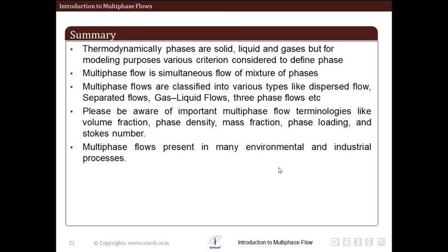So to summarize, what you should take home from this lecture on the basics of multiphase flow is that thermodynamically there are three phases, that is solid, liquid, and gas. But from a modeling point of view or an industrial point of view, we have different criteria for defining phases, and we may have a liquid-liquid system, but still treat it as a two-phase system. Or on the contrary, we may have a liquid-gas system, but treat it as a single-phase system, depending upon whether they fit the criteria or not.